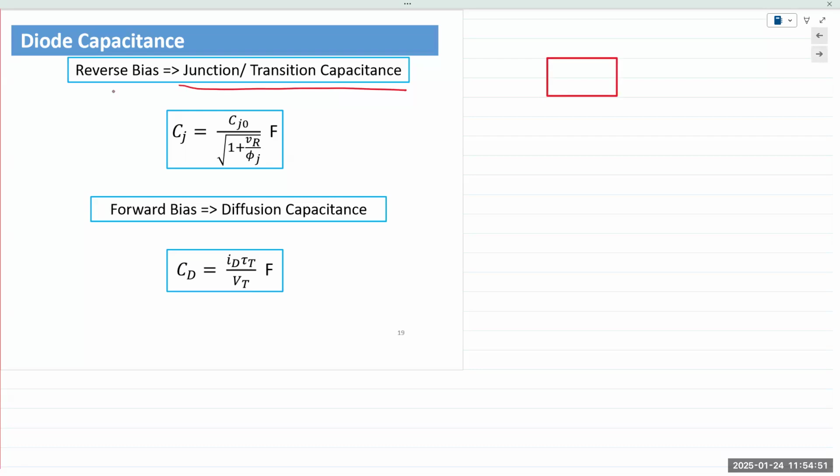So if you remember the silicon wafers I brought in a few classes ago, let's say this was the N-type material, and we create a P-type material on top of it, or vice versa, it doesn't really matter. And so this is the top view. We have an N-type silicon wafer, we create an opening in there, we implant perhaps boron, a column 3 element. So now we created a P-type material in there.